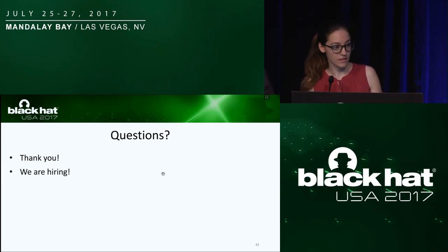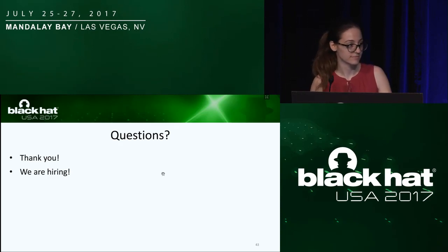If you look at the JTAG spec, it has a very complicated state diagram, and the moment that you take it out of the system, it's in an undefined state, and you basically need to do the very same thing. It doesn't provide anything more than what you already have. And another point is the moment that you remove the DIMM from the DIMM socket, it doesn't have power, so you might have some memory degradation there. In our attack, you don't have that, as long as you do the refreshes.